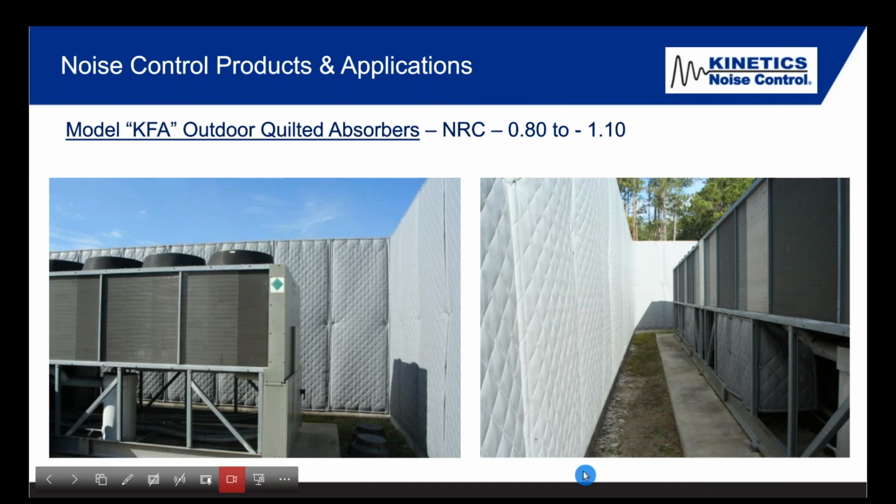You can also use an outdoor version of that quilt. We're always looking at a budget. You're either retrofitting noise control, thinking, wow, we didn't plan that money in there, but we're getting noise complaints, or it could be a new design. In a retrofit, if the budget is limiting, then you can use this outdoor quilt. Put furring strips behind it, and you can line the walls with it.